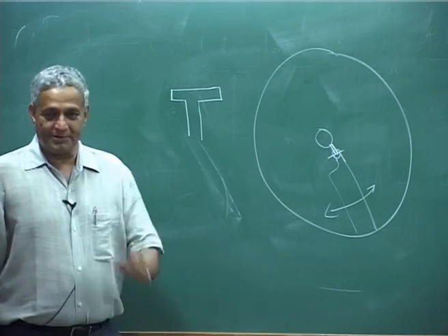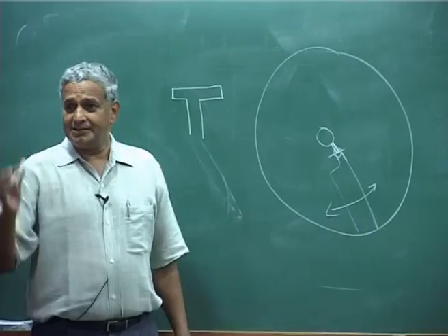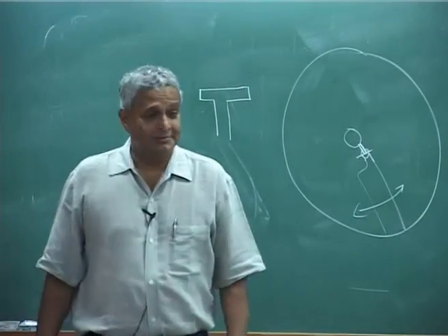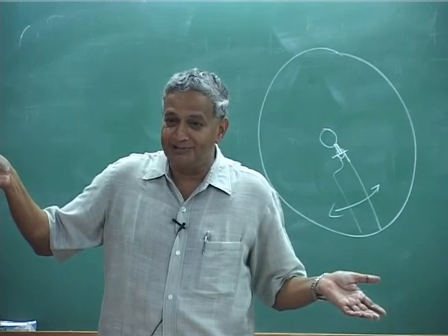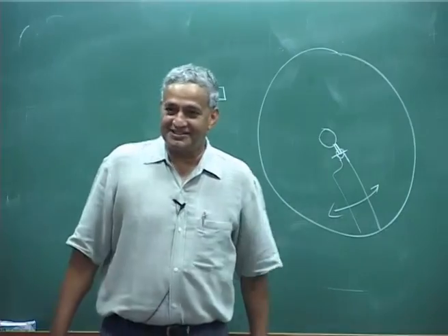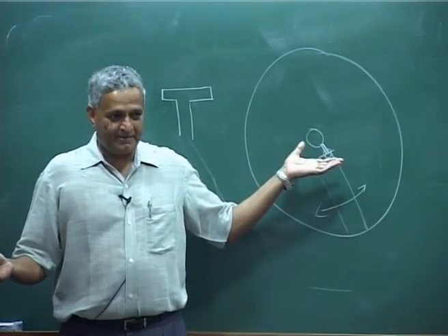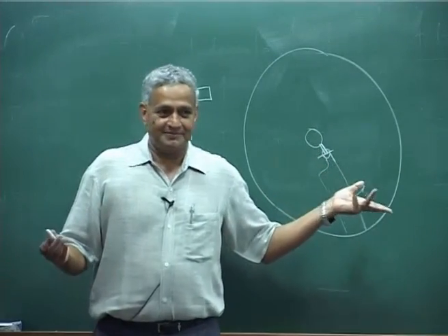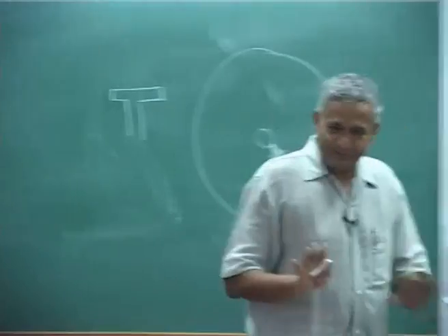Because if I put a ball bearing, attach the rotor, and in the inner race I attach the shaft, you rotate the shaft, the blade will just stay as it is, it will not rotate. You follow? You have to have an offset, and of course the offset comes because of physical constraint also, because you need to transfer the rotation. Is this clear, or to an extent?